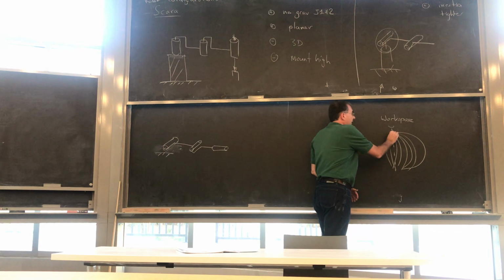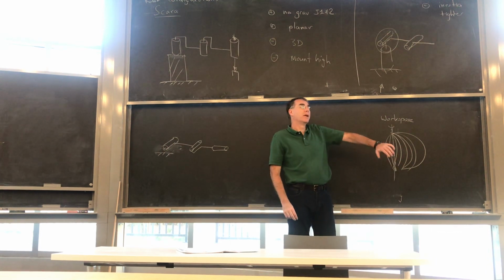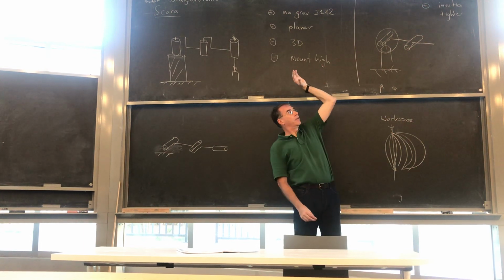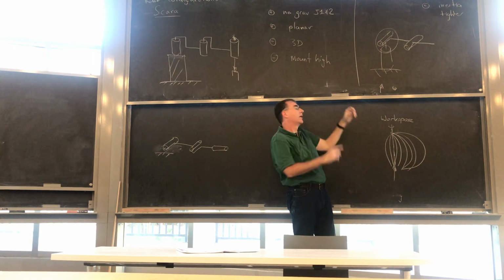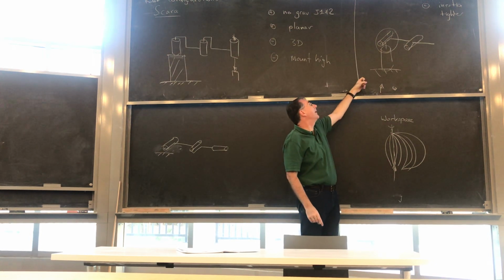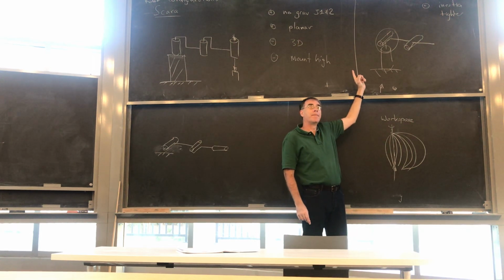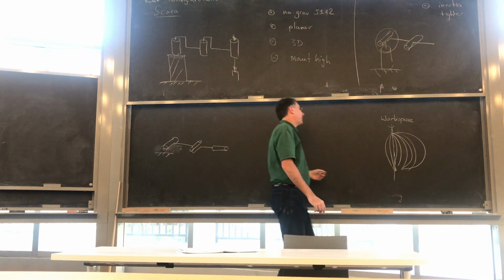And you can see the similarities are in that pole. Which means if I take this thing and I go straight above, then I can spin my bottom, but it doesn't actually move my point anymore, right? So this arm fundamentally doesn't like being straight up and down. That's its blind spot, its singularity.